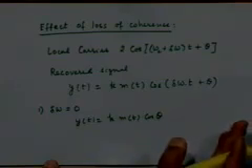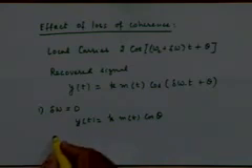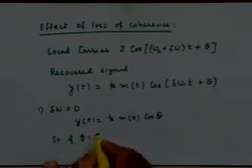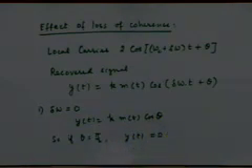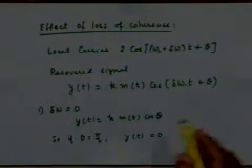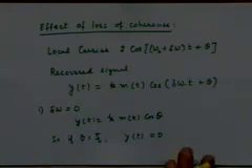But see what will happen if theta is pi by 2. You lose the signal, right? If theta is pi by 2, y(t) is identically 0. So basically cosine theta now becomes an attenuation factor, right? The recovered signal is of course just a scale, there is no distortion in the recovered signal. The recovered signal is still proportional to m(t), but the problem may be that you don't have a recovered signal at all, particularly if your phase difference is as much as pi by 2, right? So you can see there is a perfect phase matching required, phase synchronization required. Is that clear?